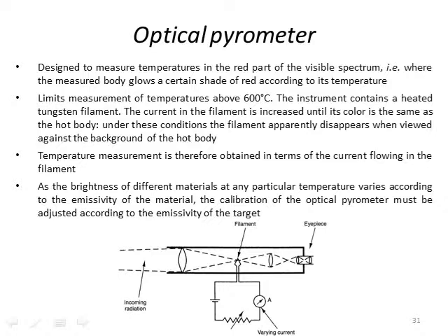When the two colors match in the detector, then whatever voltage characteristic versus temperature you have for the filament will tell you what temperature is being detected. This says eyepiece here. There are older instruments where you would actually just look into one of these pyrometers and gauge the colors yourself, but now they have detectors that detect these colors, to be a relatively inexpensive way to measure temperature.